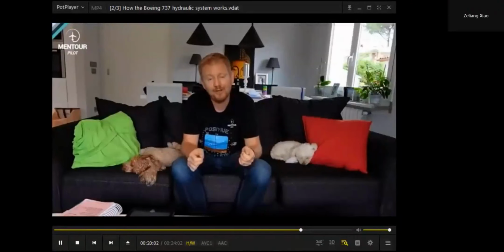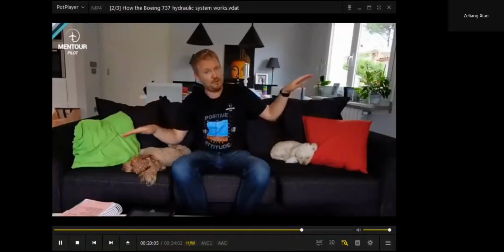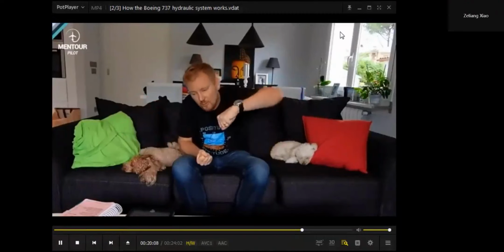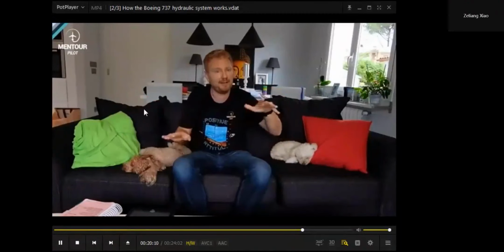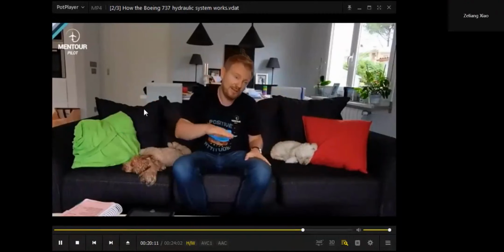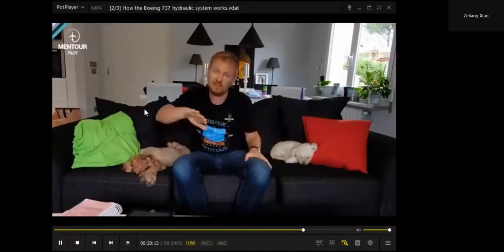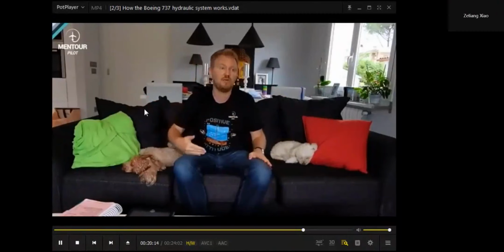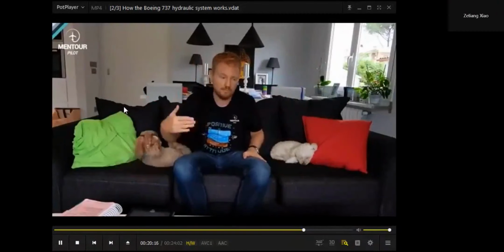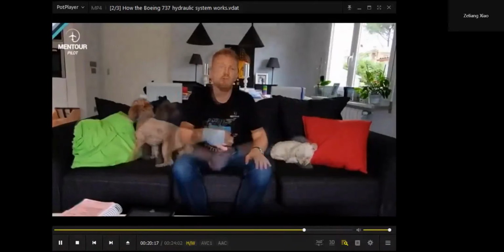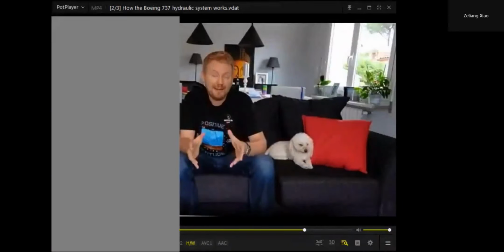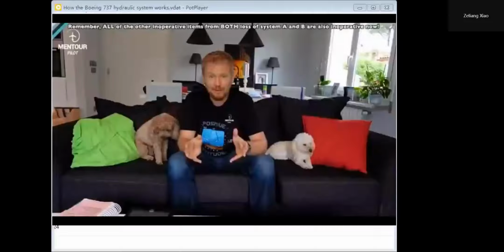So you need to be careful. You need to plan this really, really carefully, guys, because you don't want to go into normal, maybe 30 degrees bank. That's going to be way too much. It's going to take you way too much muscle power to get it back level. So plan for maybe 10-15 degrees of bank, which will give you a much bigger turning radius. So in this case, plan for a really long final, right? It's going to be a struggle to do this.